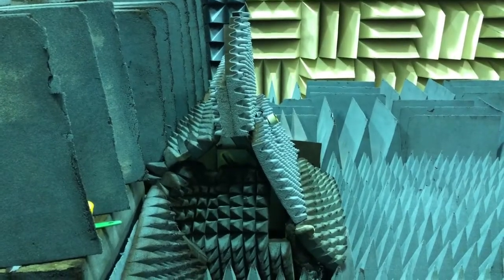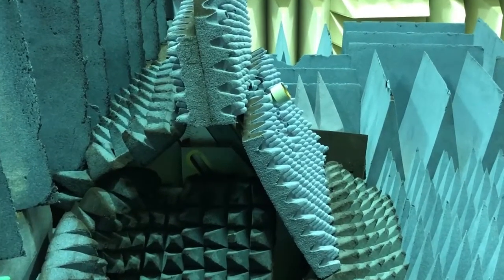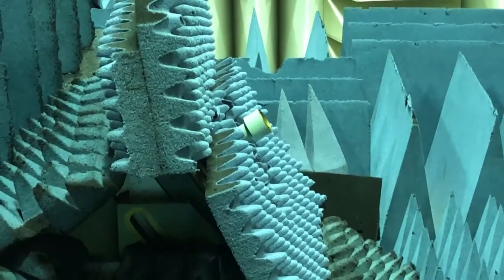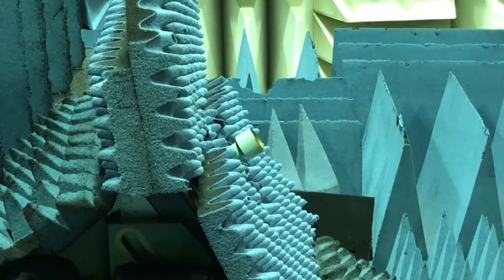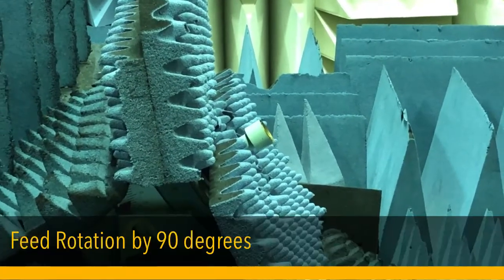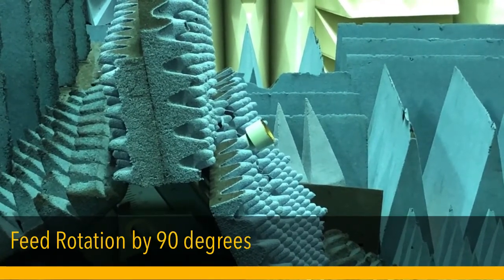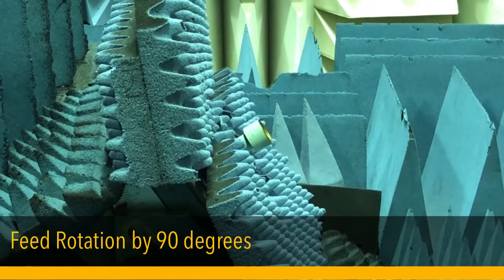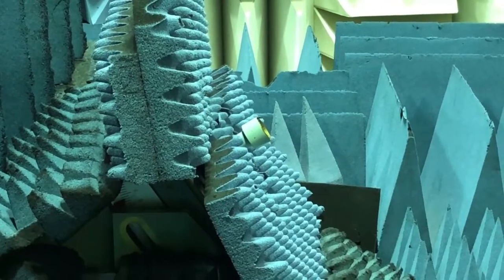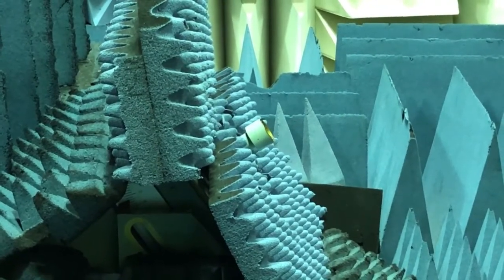As noted earlier, this is the feed of the reflector. You see that this is a structure that is covered with absorber. If you want to change the polarization of the system, you need to rotate this feed. So now we're going to show you how the feed is rotated. I'm asking Ehsan to rotate it, and now it's actually rotating. It's hard to see, but now it has been rotated. So essentially, we change the polarization of the plane wave.